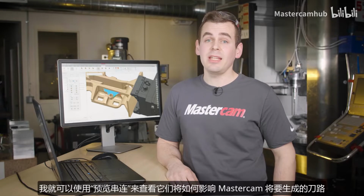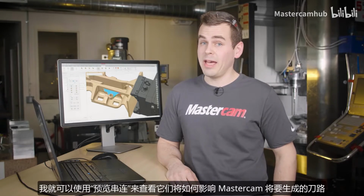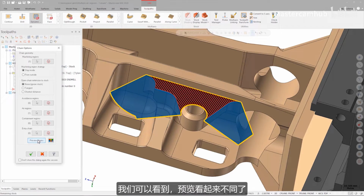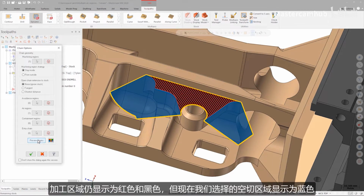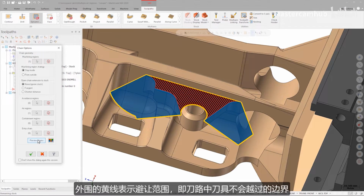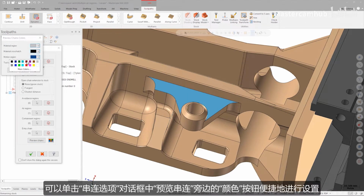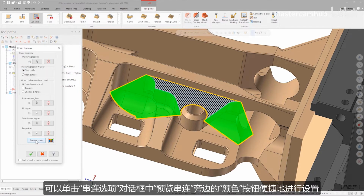Once these air regions have been specified, I can use Preview Chains to see how they are going to affect the toolpath that Mastercam creates. As we can see, the preview looks different this time. The machining region is still being shown in red and black, but now the air regions that we selected are shown in blue. The yellow line around the outside shows the containment boundary, which is the border that the tool will not move beyond. If I want to customize these colors, I can easily do that by clicking the Color button next to Preview Chains in the Chain Options dialog.